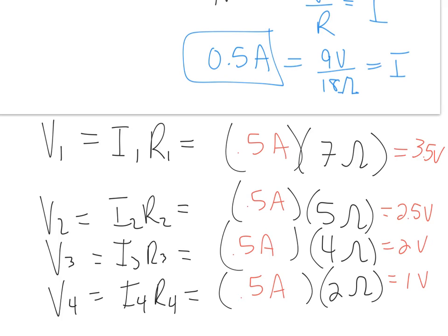Remember we talked about this? There's that EMF, we talked about that term. So the battery itself has a little internal resistance. The wires have resistance. The switch has a little bit of resistance. So there's some voltage loss to the other elements in the circuit. So when you sum these two voltages together, you don't get exactly the 1.5 that you started with. Okay? Does that make sense, the idea?